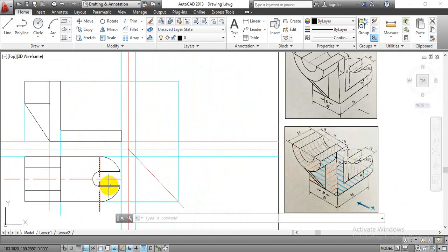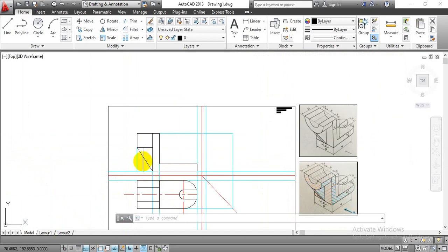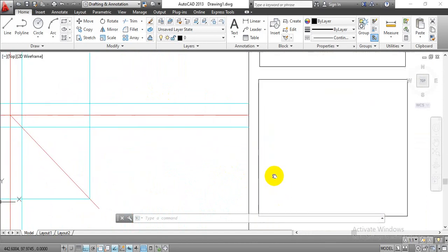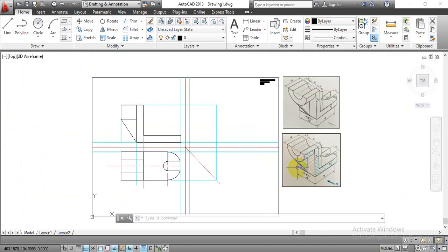So this is nothing but the outline for the top view projection. So observer is going to observe this rectangle, this curved surface, this rectangle along with this base geometry they have given. Okay, so that we have completed over here. Now to have the side view projection, if we just imagine the side view projection, we need to draw two semicircles by referring this center point, and we need to extend these vertical lines for this height equals to 80 mm and horizontal line for the width is equals to 60. So we can imagine one rectangle over there, isn't it?